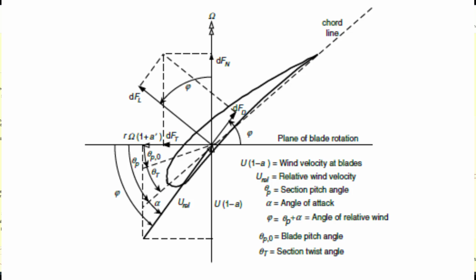When it comes to wind turbine blade design, in the previous videos we have done on this channel, we have mostly focused on the design of a blade where geometry parameters are already known. But in reality, however, one needs to generate a geometry using the available BEM formulas. There are formulas that can help you to estimate the different angles for twist, angle of relative wind, as well as the angle of attack.